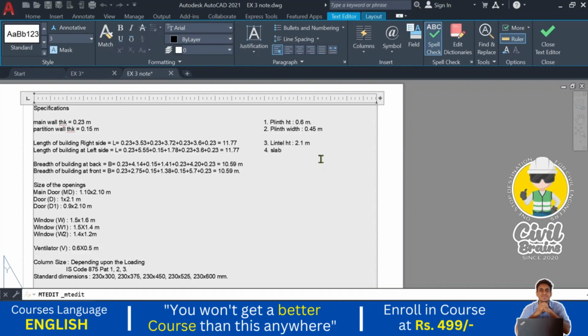Okay, next, slab height we have taken here, that is 3.2 meters. Okay, that is also the requirement of the client. He wants the height of the building to be a little more, so we have taken here 3.2 meters. Normally we are considering the standard height is 3 meters, not less than that. So standard height is 3 meters, so here we are considering 3.2 meters slab height.